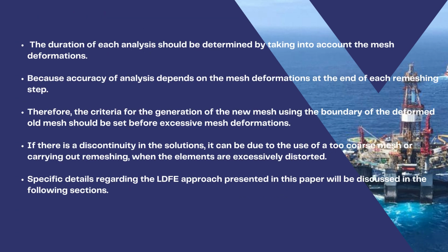The duration of each analysis should be determined by taking into account the mesh deformations because accuracy of this analysis depends on the mesh deformations at the end of each remeshing step. Therefore, the criteria for the generation of the new mesh using the boundary of the deformed old mesh should be set before excessive mesh deformations.